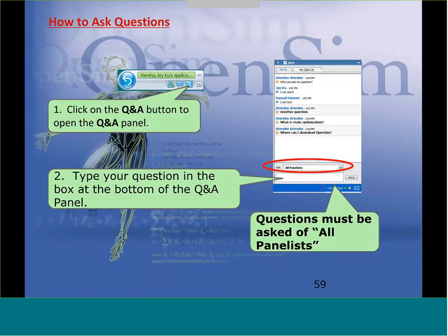Then the finite element model that I implemented for my first example was also very simple to create because it only included the meshes for the 3 implant components, the femoral component, the insert, and the tibial component, and it was just a matter of positioning and aligning it to the local coordinate system of the knee in OpenSim.